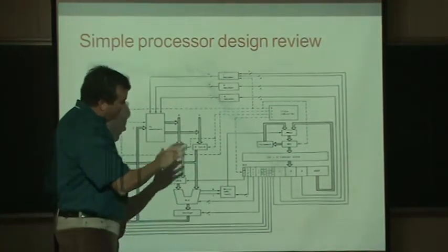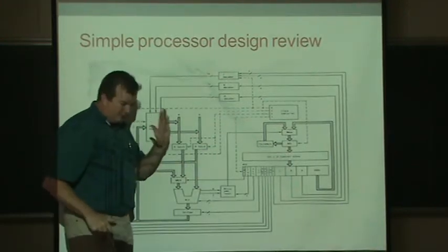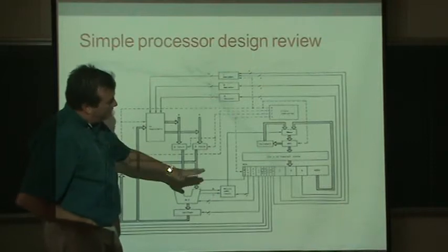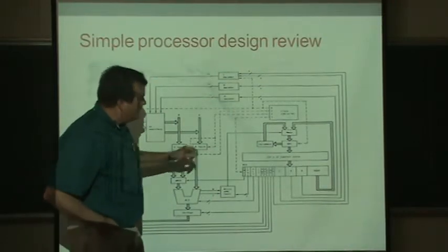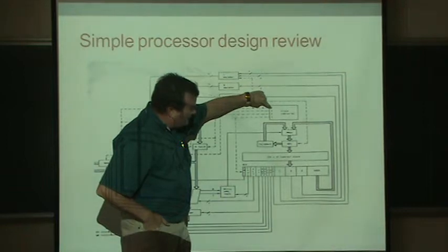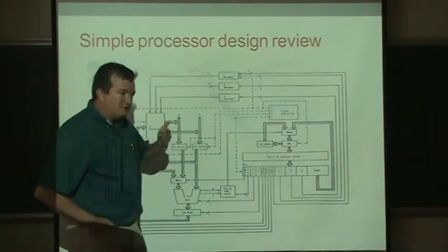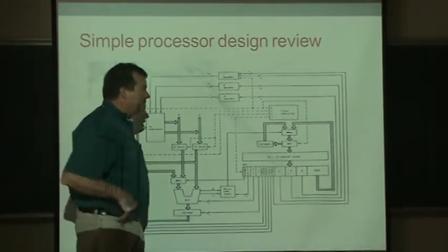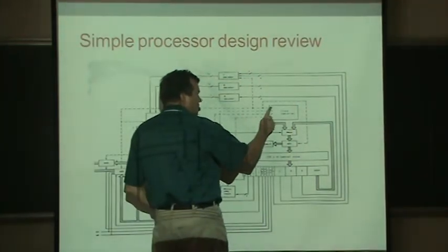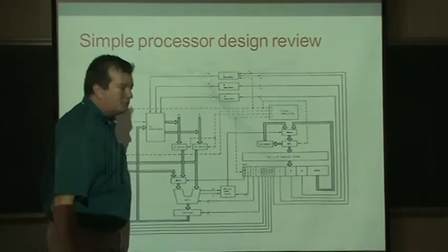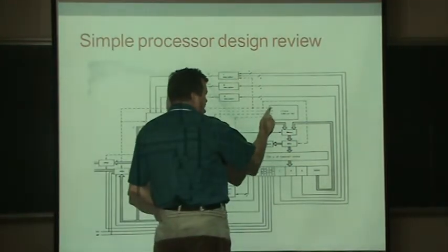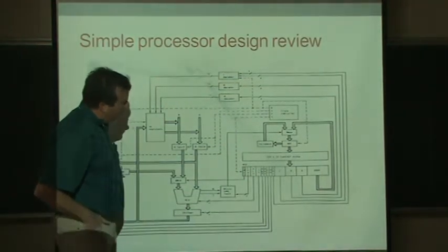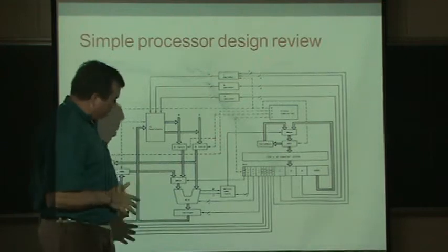So with this design, and maybe next semester I'll redraw this picture but using 5 stages instead of 4. In this case, we're actually doing the fetch simultaneously with the write of the previous instruction. So I think it would have been a little bit more clear if this said 1, 2, 3, 4, 5. So maybe what I'll do next semester is just separate this step 4, break its 2 parts up into a 5th step. Okay, but forgetting about that for now,